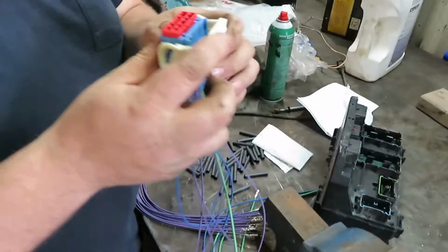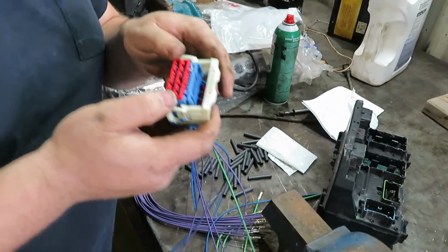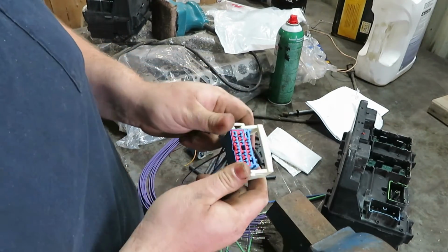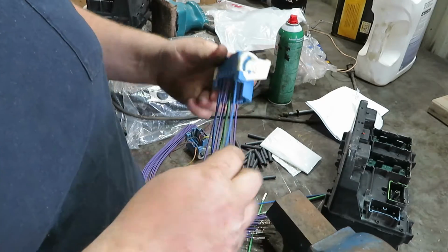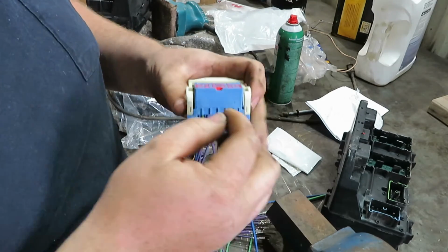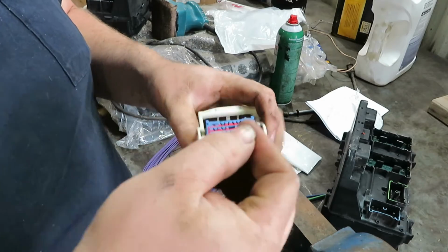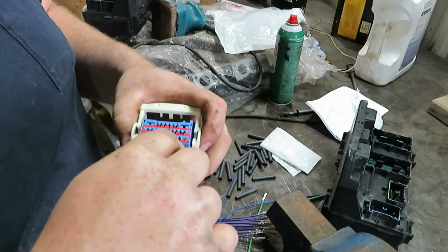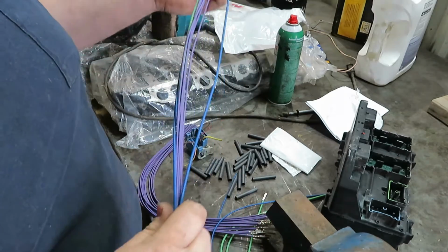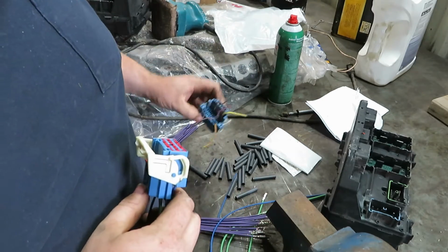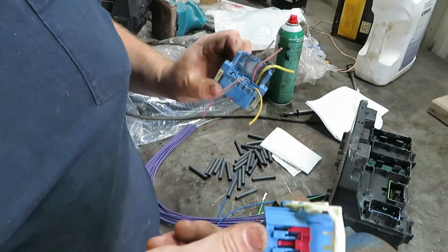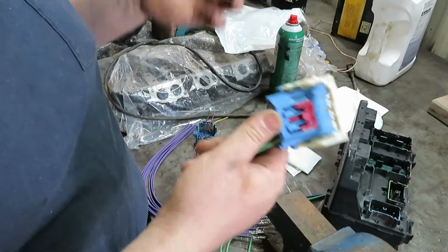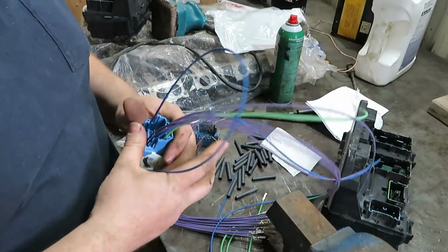Now to lock them in place. This red tab is sticking up. You just push it down and that locks everything in there. So now these wires, they won't pull out unless you pull this red piece back up, and then you have to reach in with like a small pick or something and push the tab down, and then you can pull the wire back out. But as long as you put the same size wires in the same hole as the original connector, you don't have to worry about taking it back out. So let's take this back over to the truck and match the wires up and get soldering.